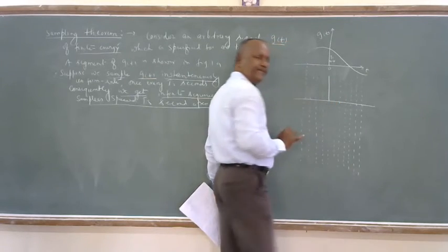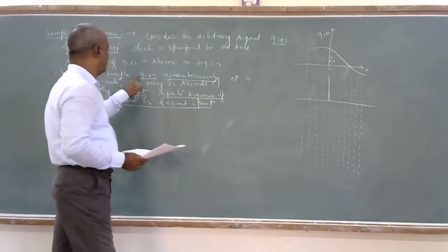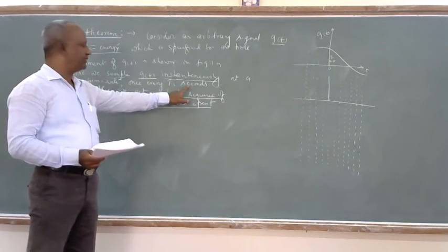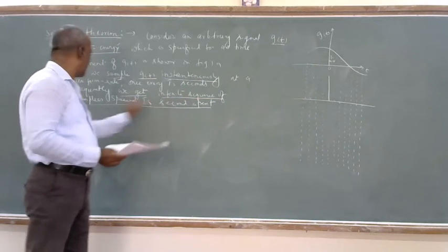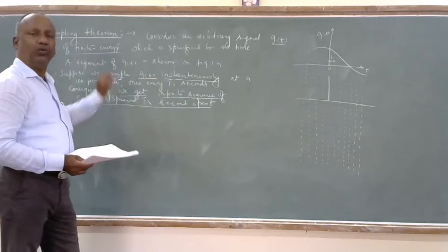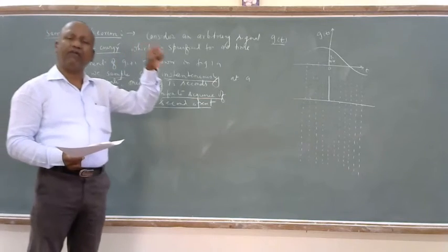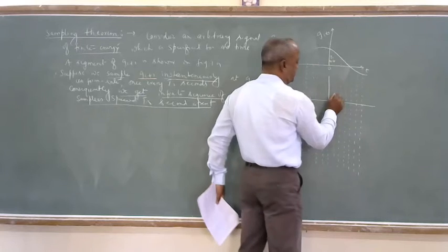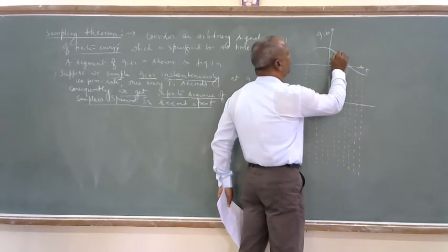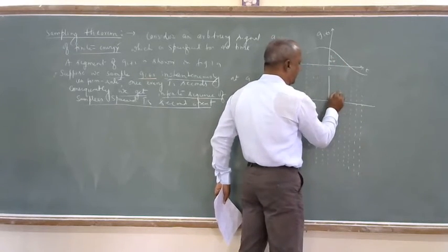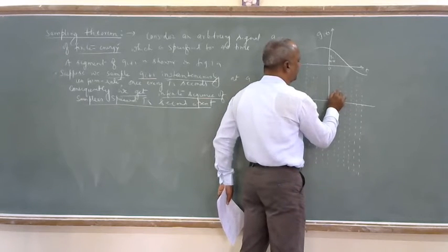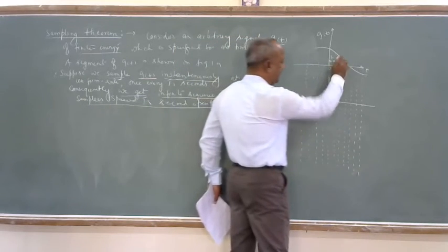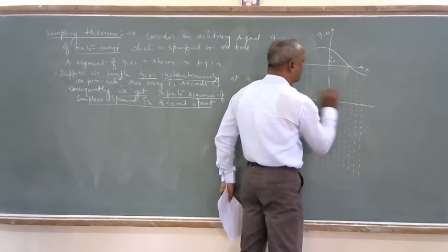So if I take the sample at a uniform rate, once every ts seconds, what do I get? An infinite sequence of samples. What samples? A sample means it is a value of the amplitude of the signal at that instant. So at this instant, for example, if it is 2.2, then here it is a dot with 2.2. This is the sample value. Similarly, at this instant, again I am getting the amplitude as a number or value.